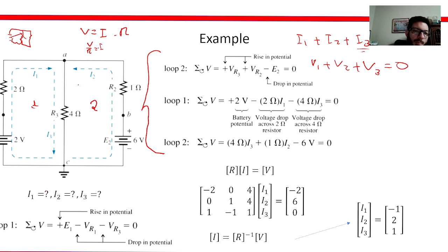But furthermore, since we have values of voltage, we want to use known values of voltage. So let's go ahead with this equation because we have some of the voltages and then some of the other voltages will be unknown, versus here all the currents will be unknown. So let's set up the voltage equation and then start it right here. So loop 1 is this loop right here, and we're gonna go through all the voltages.